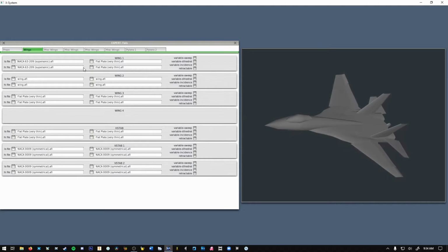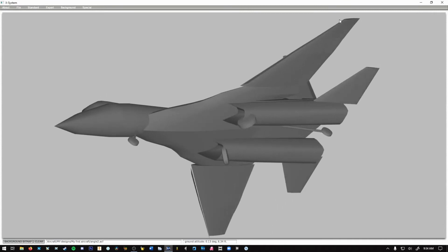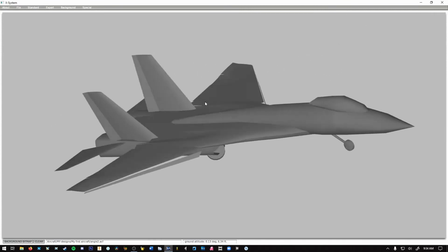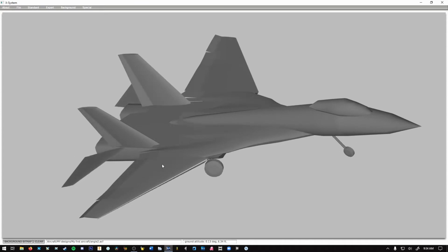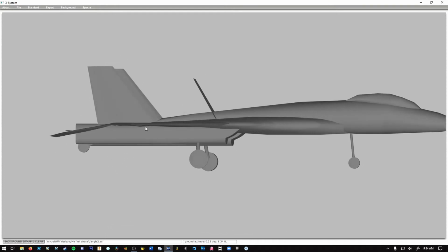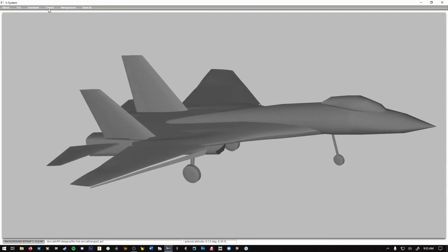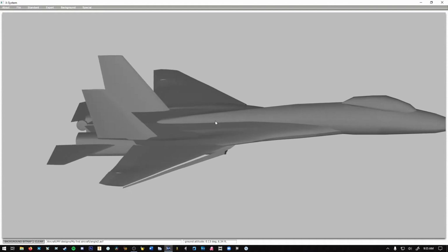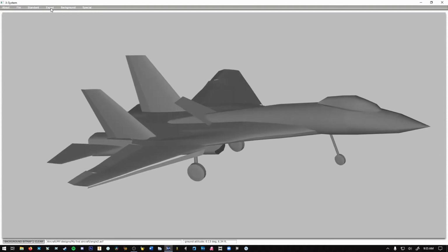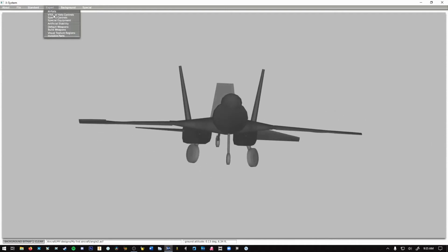While that's fine for most applications, what it means is if you have a fighter like this one that has leading edge root extensions, which are supposed to create vortices under the leading edge of your wing to give you more lift at high angles of attack, it just won't happen in X-Plane because it doesn't model that type of airfoil. So you have your 20 degrees maximum angle of attack of the wing, and then you have 8 more degrees that slats will give you. That means that unless you have thrust vectoring, which I do, but we're just going to ignore that for now, the most angle of attack you will be able to sustain in flight in X-Plane is 28 degrees.